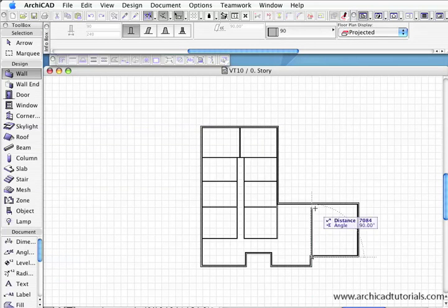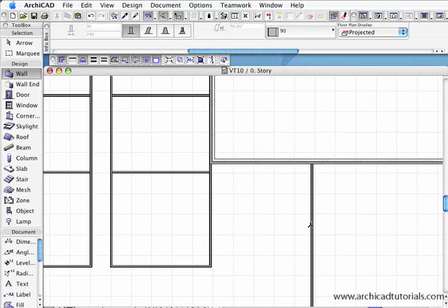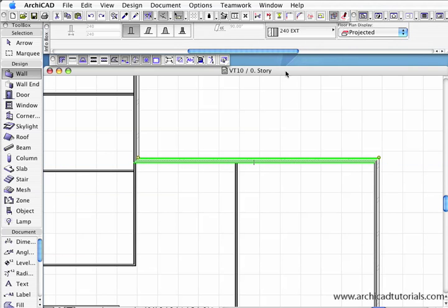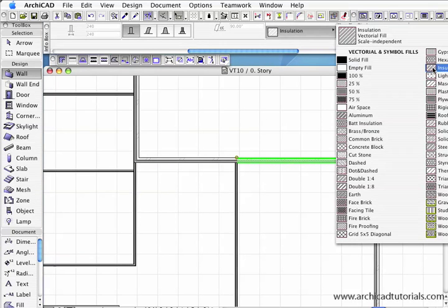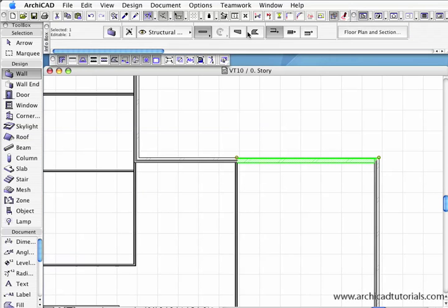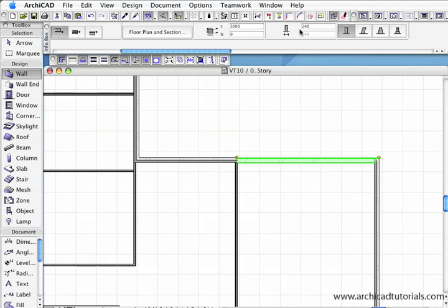Then I might need a wall going up here, which means this wall here wouldn't be brick veneer anymore, it could be a solid brick wall. So I click on the axe tool. Now the guides come up there, hold the shift key, and it asks me which side I want selected after I split it. So now I'm just going to change that to a single brick skin wall. I'm going to change the thickness of it to 110. That's a 110mm brick wall.